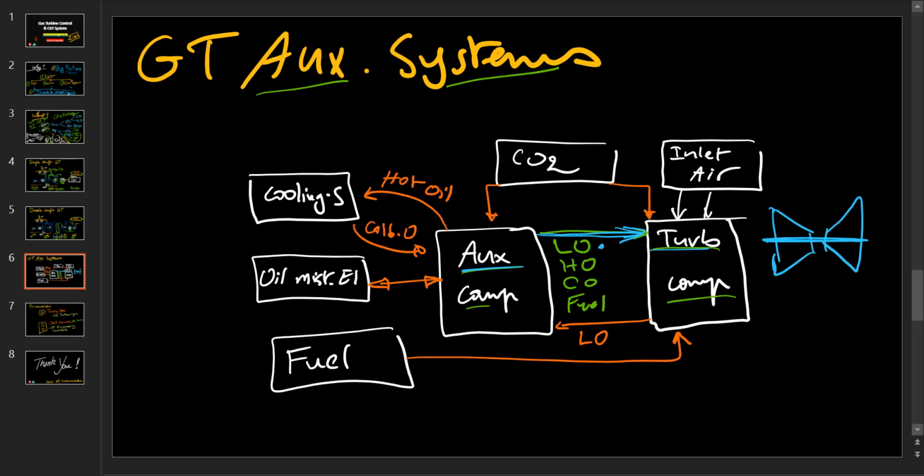So through the bearings, oil is being fed there to cool the metal to metal points, to cool the shaft and to transfer the heat from the metals down to the lube oil tank. We'll see that in the coming videos.